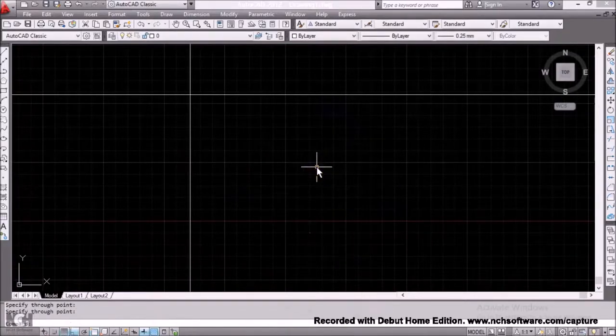So that is how to use the construction line, and you can start using the offset tool to get what you want. It is very essential, and at the end of your offsetting, you have to trim off the excesses that remain. So you use it to produce your initial concept, and after everything, you remove the parts that you don't want to use. That is about the construction lines in AutoCAD.